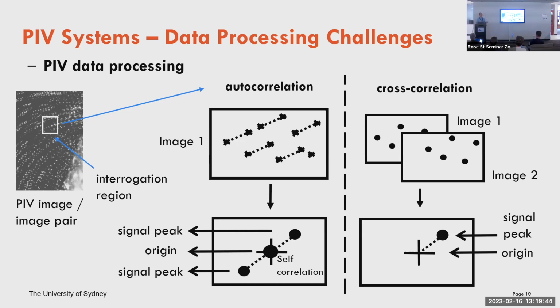So everything gets better when you cross-correlate, and everything now is cross-correlation. It's very rare that you find autocorrelation, but you can still use autocorrelation to check your signal quality, for example. That's a common thing in signal processing. But so we're all in a kind of cross-correlation regime.